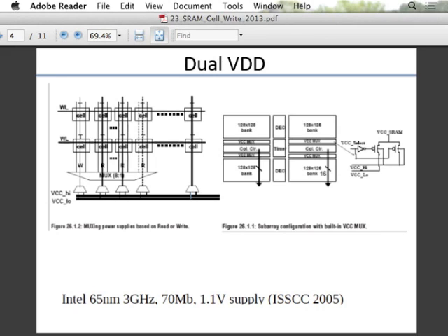The question is, is it a normal mux? Now, of course, what is the definition of normal? We don't know. On the right side you see this, right? The mux essentially consists of two PMOS transistors. That is sufficient. It's like a pass gate. Because you are passing only the high value signal, you don't need the NMOS. So that is why you have these two PMOS transistors.